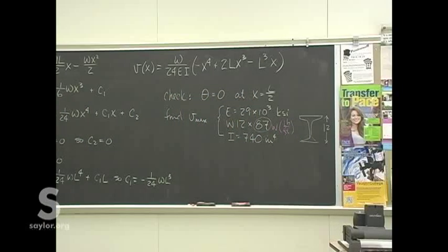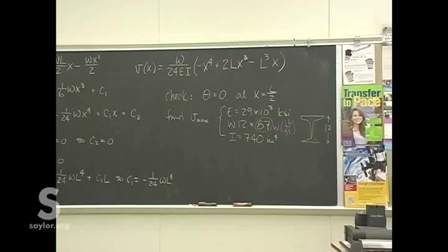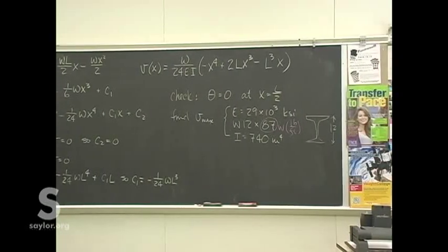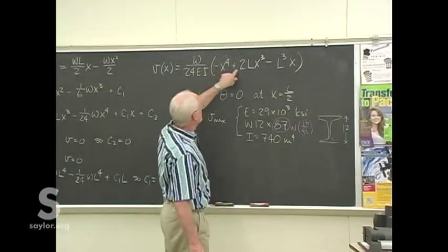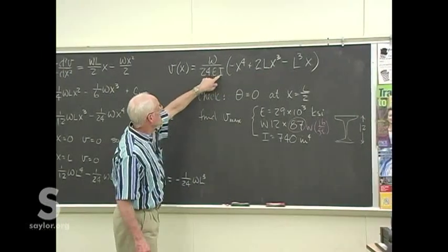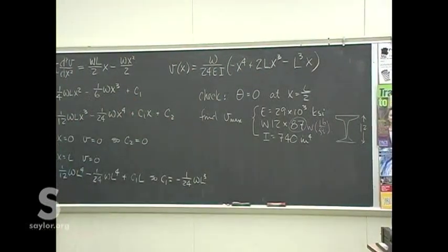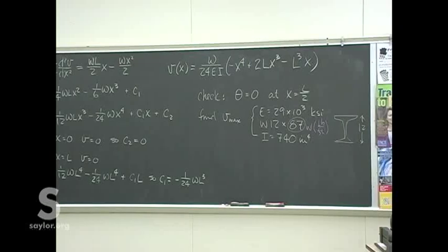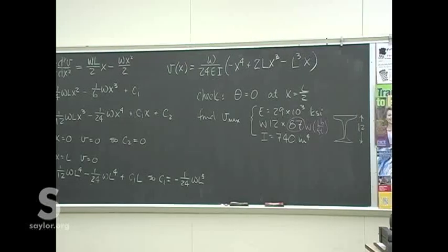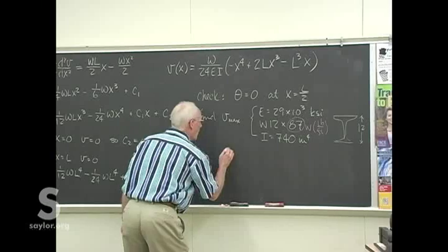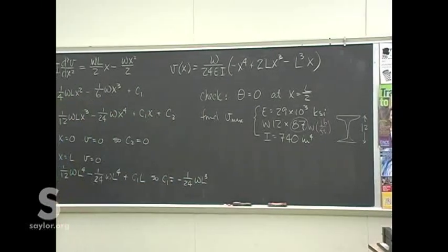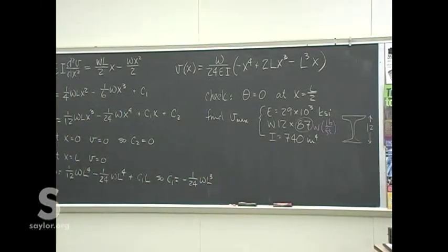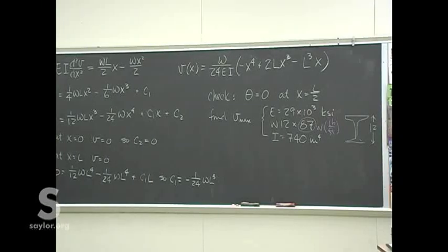So you can figure out real quick what the maximum deflection is at the center of the beam. Just put in L over 2 for X, the EI and W we have for that beam, and then watch your units so we can see what it looks like. Oh, and we need a length of the beam here, so we'll pick a good beam, 18 feet.